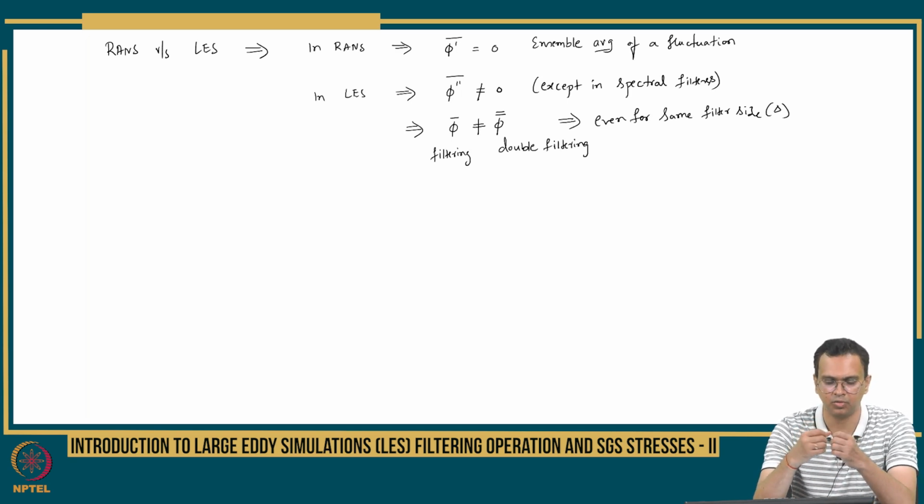If you take two counter rotating eddies, there is a shear between them, and we are looking at high momentum or high inertia, right? Reynolds numbers are very high, so inertial effects are dominating over viscous effects. So you have shear, you have nonlinear interactions, so the vortices do break up. Many factors are there. They can amalgamate also, form a bigger eddy, and break up again.